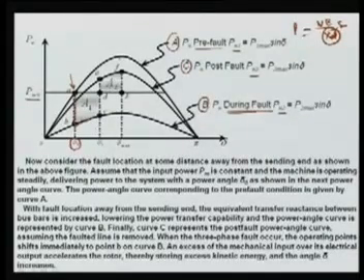Now in this case your PE which is fed to the infinite bus is reduced because here the PM is more and PE is less, so machine will accelerate. Accelerate means here your delta will increase.